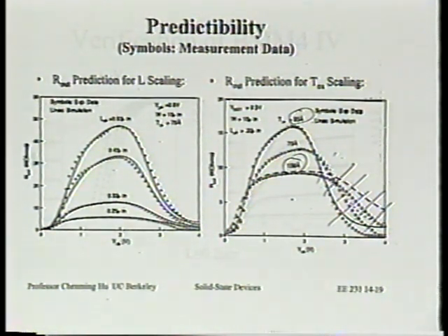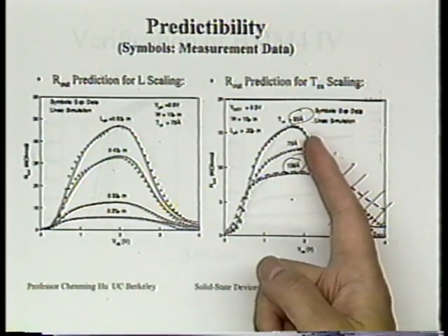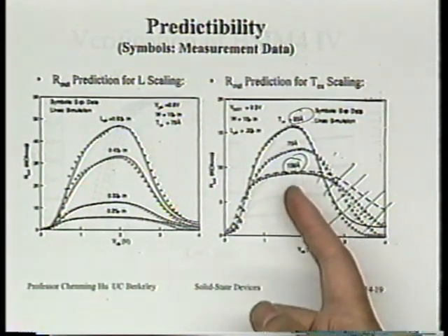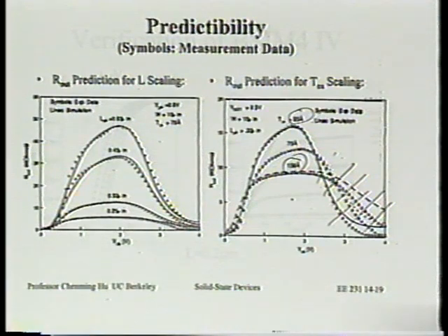All right, let's think through this then. What does thin oxide do to the DIBL effect? Let's agree that thin oxide suppresses the DIBL effect. If we suppress the DIBL effect, how would that affect R out? When the DIBL effect is taken away or reduced, does R out rise or fall? Joe, what do you think? The R out would increase. R out would increase. The IV curve becomes flatter. That means R out increases. And that's exactly what you see, right? Thin oxide has the largest R out here, right? Smaller R out. Is that right? Yes? Okay, next.